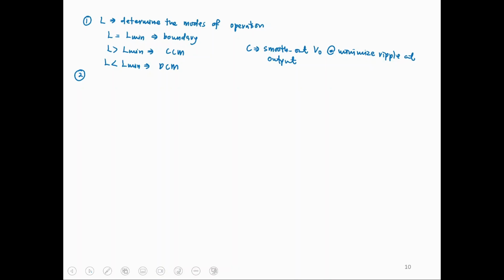So as you increase your switching frequency, the value of your L will decrease as well as the value of your C. As you increase your switching frequency, the losses will be increased, the heat of your circuit will be increased, the efficiency will be decreased. So this one will require a heat sink in order to manage the heat properly.